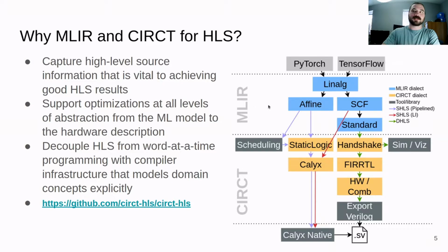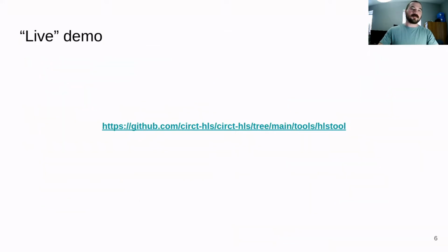When memory dependencies can be analyzed at compile time, the static flow can automatically pipeline loops and further optimize the FSM. At every step of the way, we're able to pick and choose the right level of abstraction to capture the information we care about. This allows us to focus on the particular HLS techniques we're employing and opens the door for compiler extensions at each step. Now I'm going to walk through the different flows and the IRs they use.